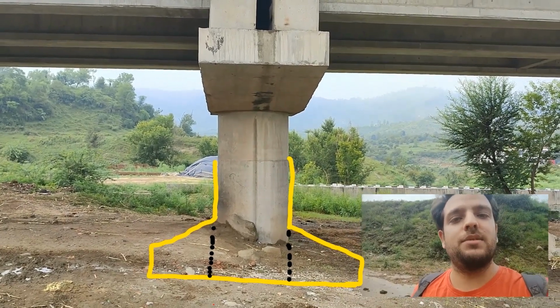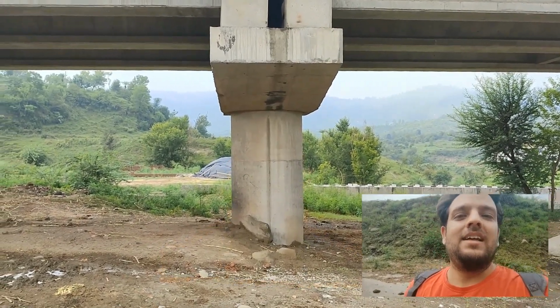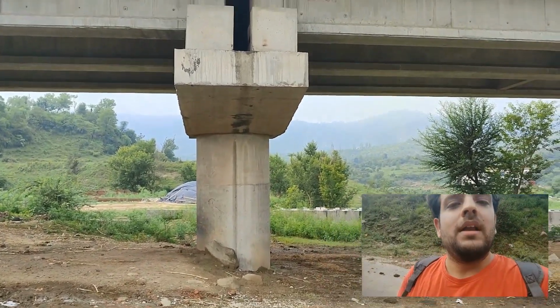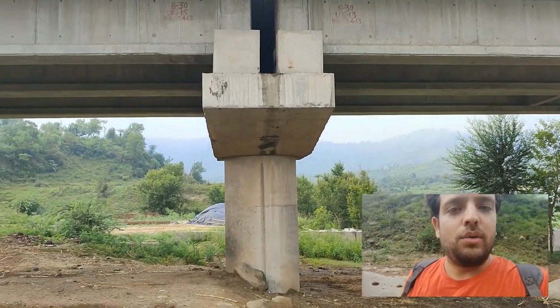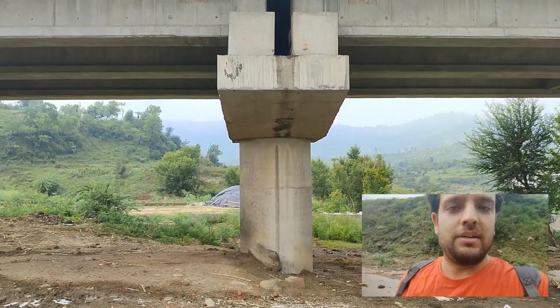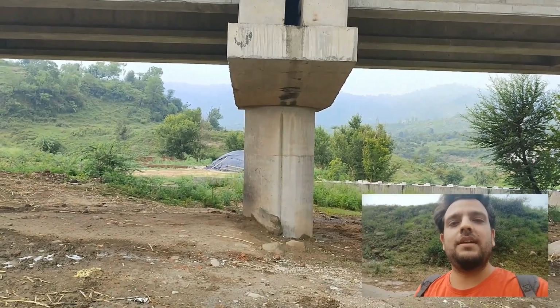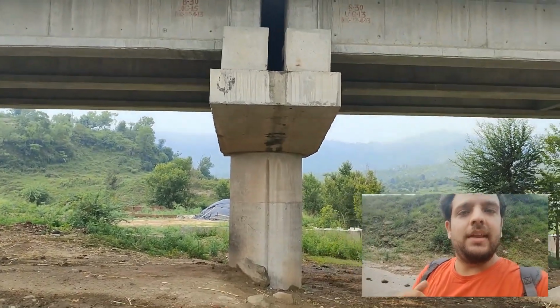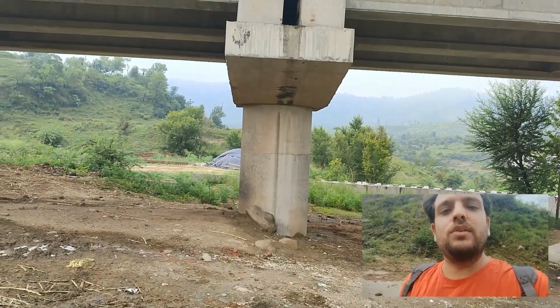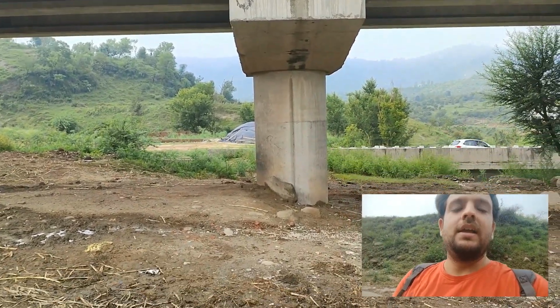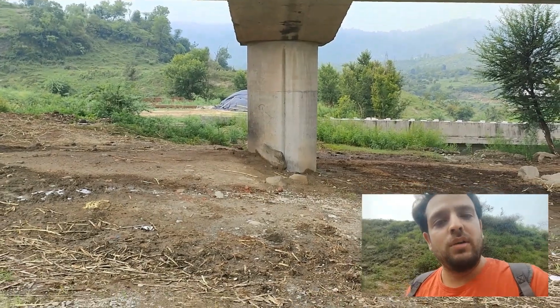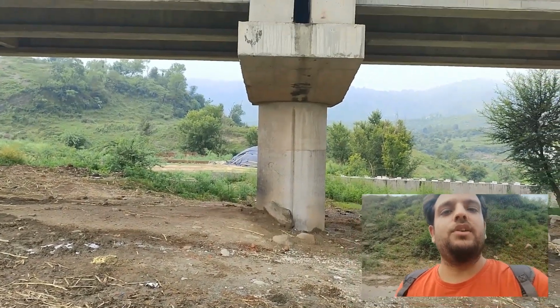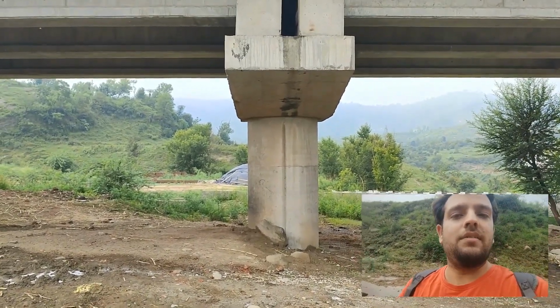a uniformly distributed load acting upwards, it is also subjected to some lateral moment in the longitudinal direction as well as in the transverse direction. But we will restrict our discussion to the longitudinal direction in this video just to limit the length of the video, but a similar concept is applied to the transverse direction as well. So just focus on how this longitudinal moment is developed simply because of the horizontal forces acting at different lever arms.